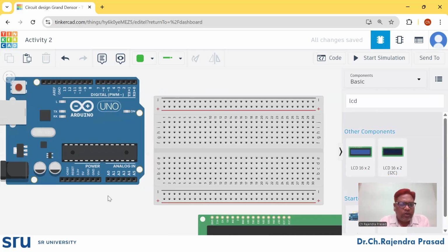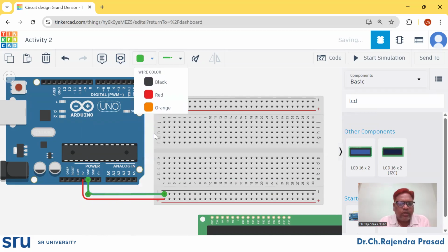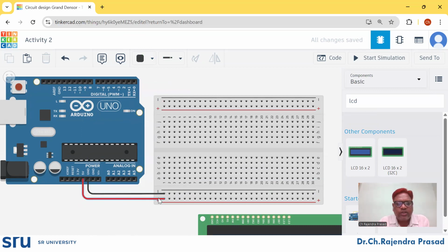When using a breadboard, in order to make a common VCC required for most of the components, you can use a common VCC and make it red, and a common ground on the breadboard, which I make black. Normally I prefer VCC represented with red color, and black color represented with ground. Now these lines become 0 volts, and all these lines become 5 volts.